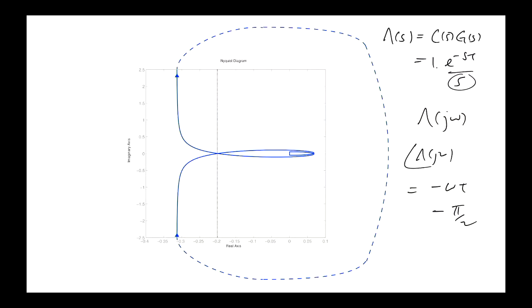All right? And then, the Nyquist D contour that we have to go around in this case, because we've got a pole at the origin, looks like this. So we've looked at what happens when we start at a small frequency and go up here. As we go around here, the magnitude will be 0, as we let the radius here go to infinity.